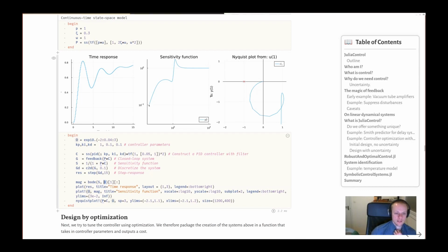That means that if we have a disturbance of a low frequency, for instance, a constant disturbance, we would be able to suppress that, meaning that that disturbance will not cause an error in our output after a sufficiently long time. And we also saw that if we let this simulate for a long time, we reached our desired reference of 1. But we also see that we have a peak here.